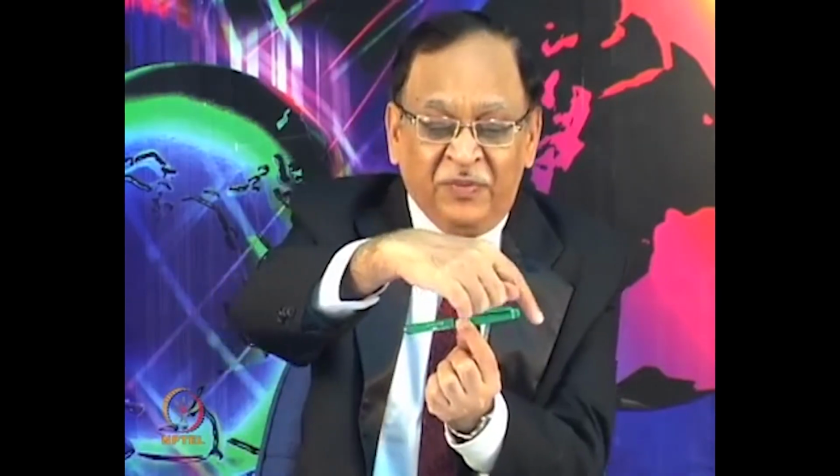So, that is why dipole antennas are also known as vertically polarized antenna, but that is only if you keep it as a vertical. Suppose if the dipole is kept like this, now this is not a vertically polarized antenna, now it is horizontally polarized antenna, because E field will be like this maximum and going here, and H plane will be around this here. Okay. So, orientation of dipole is also very important.